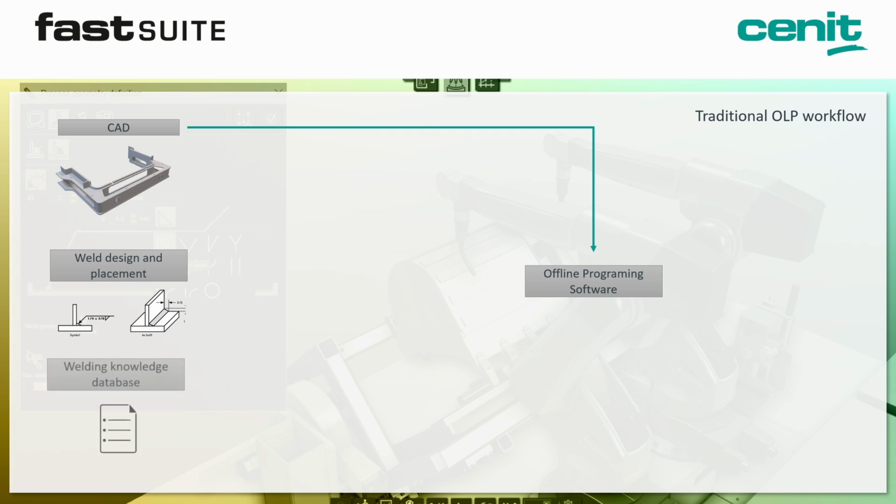On a separate side, we would also have our welding experts deciding what the settings for the welding machines would be. So let's say for a 10mm weld, how much voltage, how much current, and how much wire feeding do you need. All this knowledge is somehow stored in tables for the machines, depending on how big you want a weld to be or what position the weld is going to be performed in. Many times this kind of knowledge is acquired by testing: taking similar plates, doing some feasibility testing, and then making cuts and ensuring that the quality is what we are expecting for a specific part.